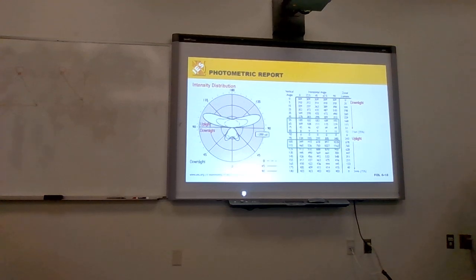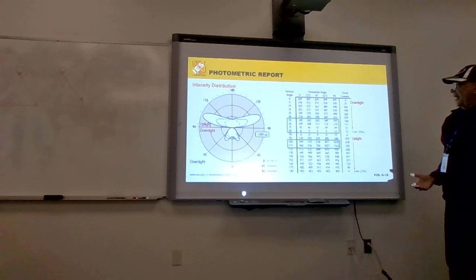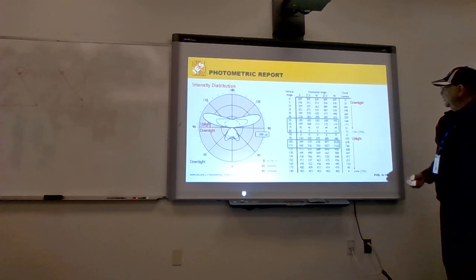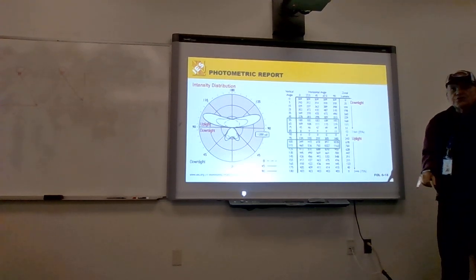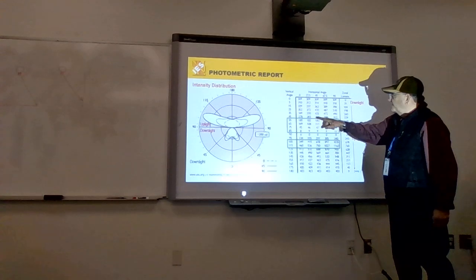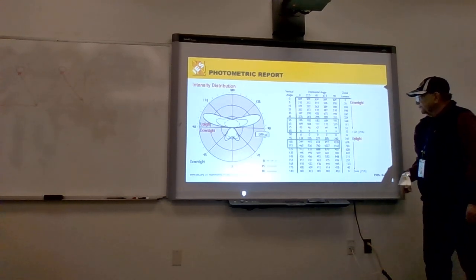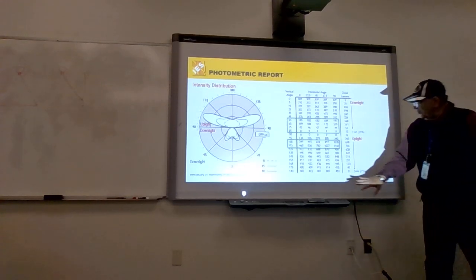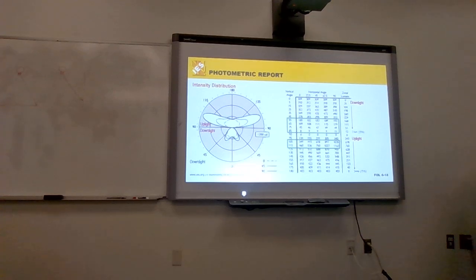Here's another chart. Remember, we're talking about a luminaire that has uplight and downlight now, like a pendant, which has an uplight component and a downlight component. And so we have to look at what's happening in both directions. So if we look at the downlight and we see here between 45 and 65 degrees, we sum total all of these candelas, and that's what this is, and we compare that to the total number of candelas, we can determine what a glare factor might be.